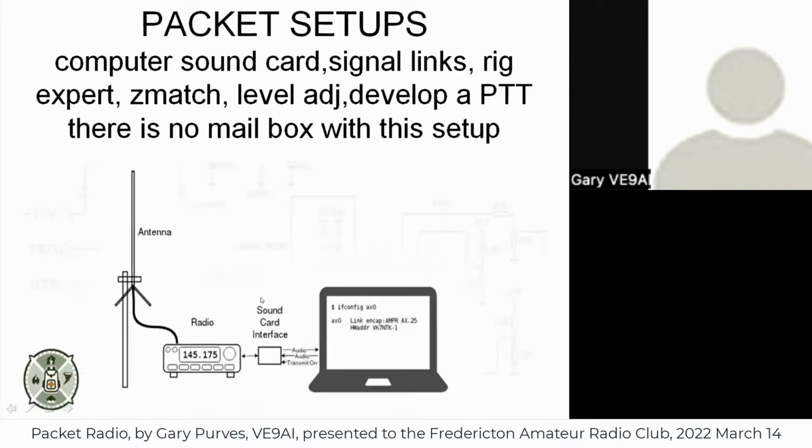Newer ones use computer sound cards, like SignaLink or Rig Expert. They impedance match, level adjust, and develop a push to talk, but there's no mailbox with this setup. We just have the computer, sound card interface and radio. So you would have to use another method. If you wanted a mailbox, you'd have to register at a PBBS and store your mail there.